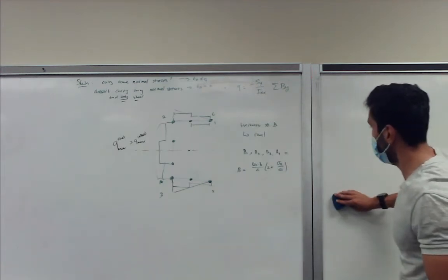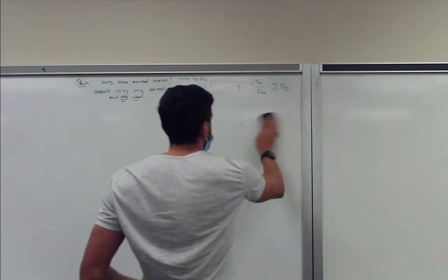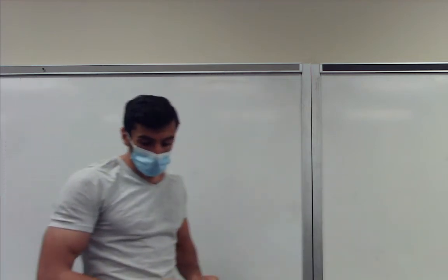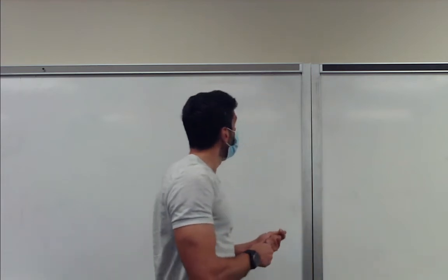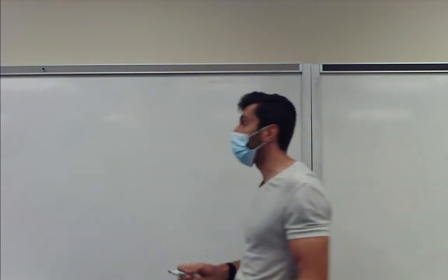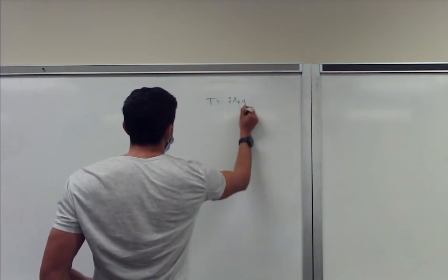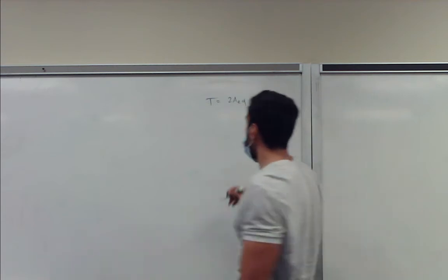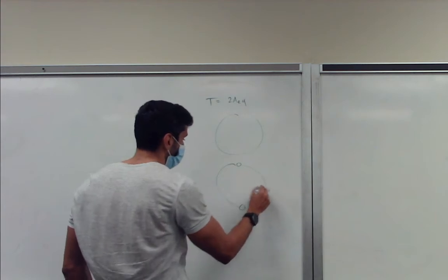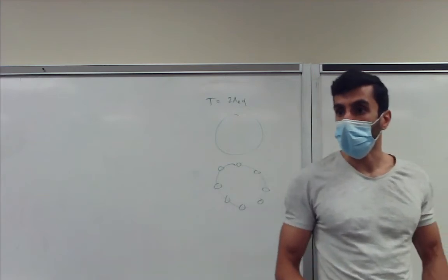Okay. And the last thing, for torsion, that's actually simple. It doesn't affect the equations. Because if you remember in torsion, what we had was T is equal to 2 times the enclosed area times Q. And it doesn't really matter if the enclosed area consists of a skin or consists of booms. The enclosed area still remains the enclosed area.